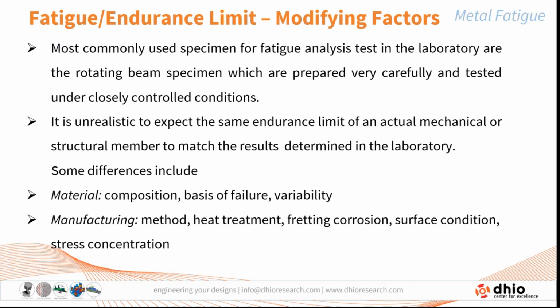So, taking all these things into consideration, one has to see how the endurance curve or the fatigue limit or the endurance limit can be modified, because the SN curve which we have drawn is going to be for an ideal condition which is available in the standards. But if all these factors which affect the fatigue life are also taken into account, then we have to see how it is going to be different from that of the standard SN curve.